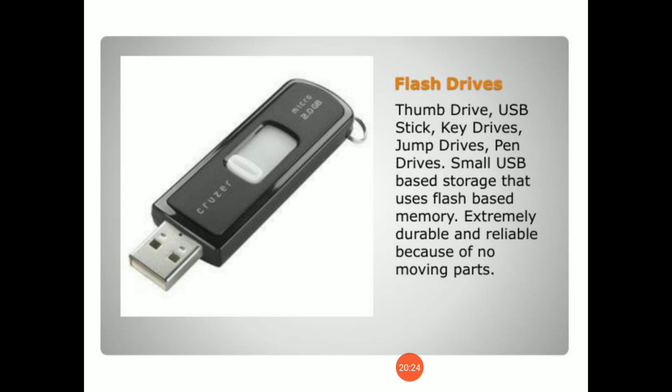And the last comes the flash memory. Flash memory is electrically erasable and reprogrammable. It is inherently non-volatile memory. Unlike EEPROM, flash memory uses a one-transistor memory cell, resulting in high packaging density, lower cost and higher reliability.